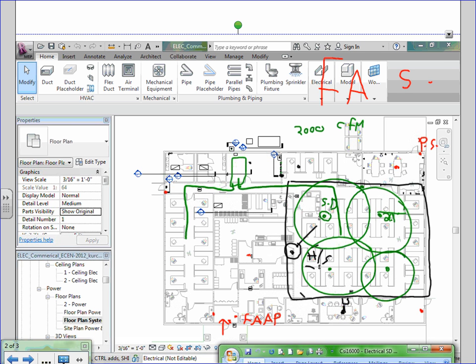Sometimes the return air is just above the ceiling. They use the entire ceiling space as your return air duct. So imagine the entire ceiling space. You pop this tile, and that's all your return air space. It all eventually gets back to the air handling unit. And then there are ducted returns, which actually have ducts that run throughout the space that bring air through and direct it back to the ceiling space, or back to the air handling unit.